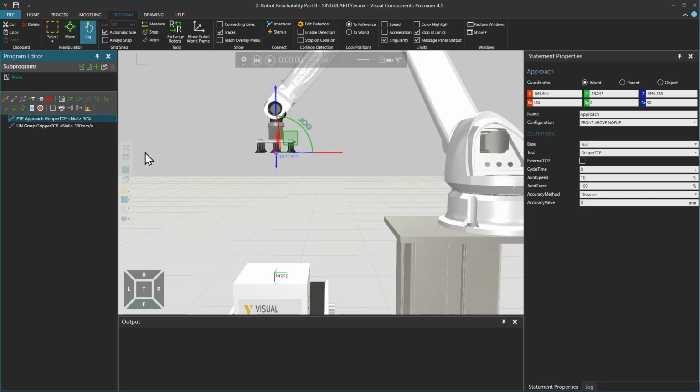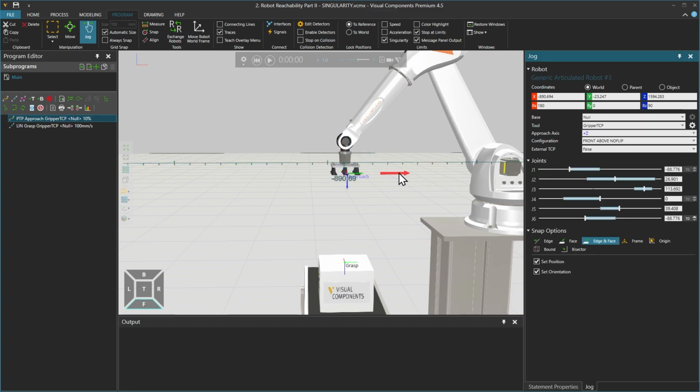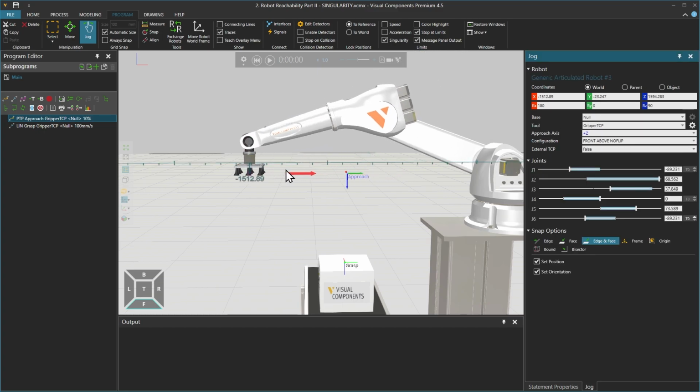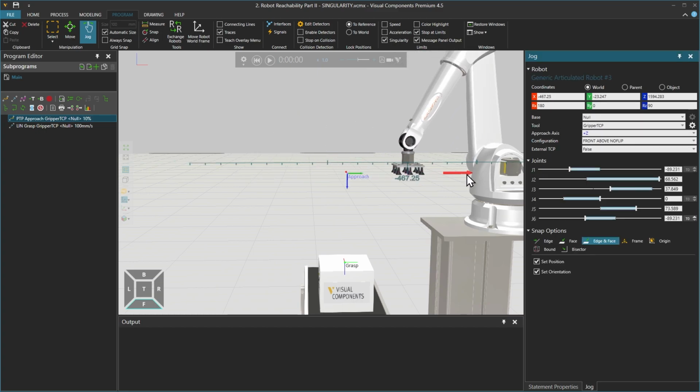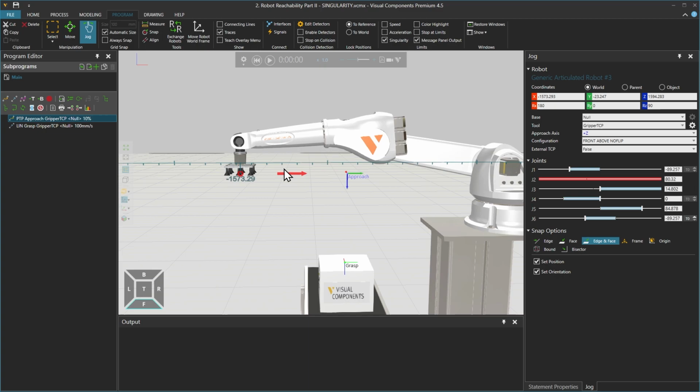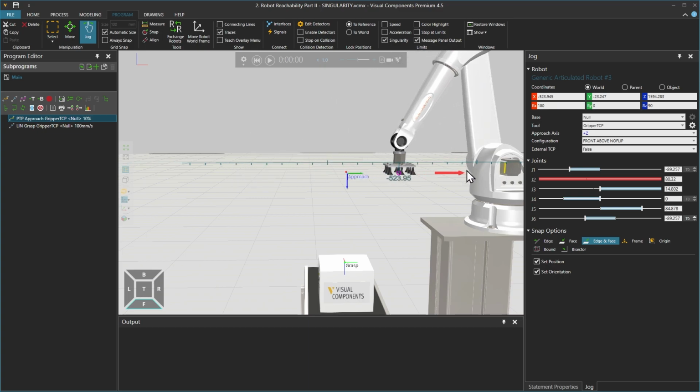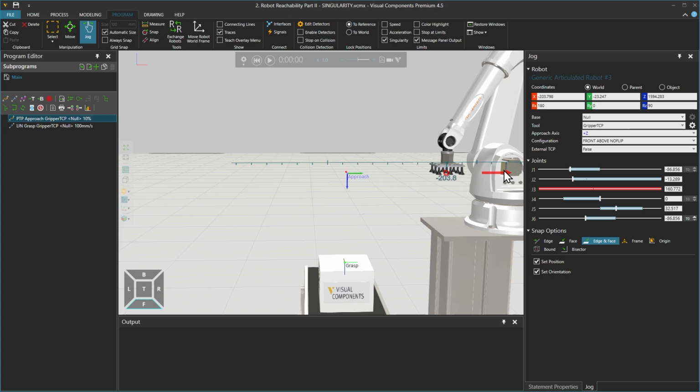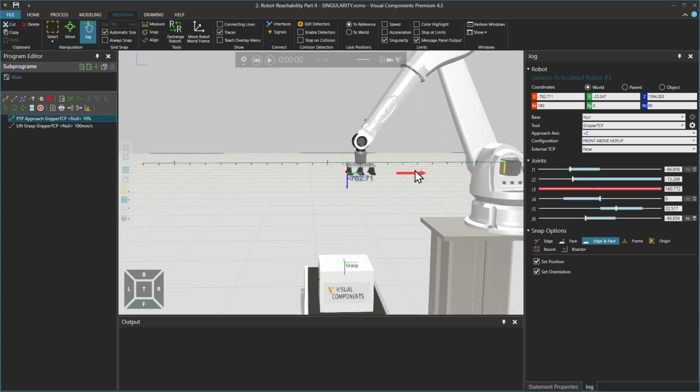When adjusting positions, you will want to monitor your joint limits. Disable stop at limits if you want to allow the joints to go beyond their limits. Using the jog tool, you can use the jog panel to monitor the joints or watch for the origin ring at the center of the position turning red if you move the joints too far.